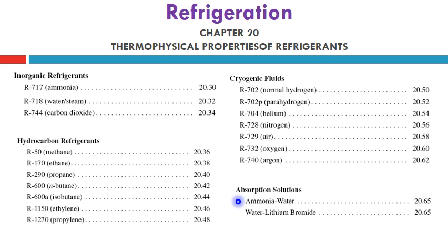The absorption solutions, not refrigerants, we can name them as solutions, which will be used in absorption cycles, vapor absorption cycles, which will be discussed in lecture number 10. They can be classified into the main solution, or may be named also as a refrigerant, such as ammonia and water, one of them acting as a solution and one of them acting as a refrigerant. Then water and lithium bromide: the water will be the refrigerant and the lithium bromide will be the solution.